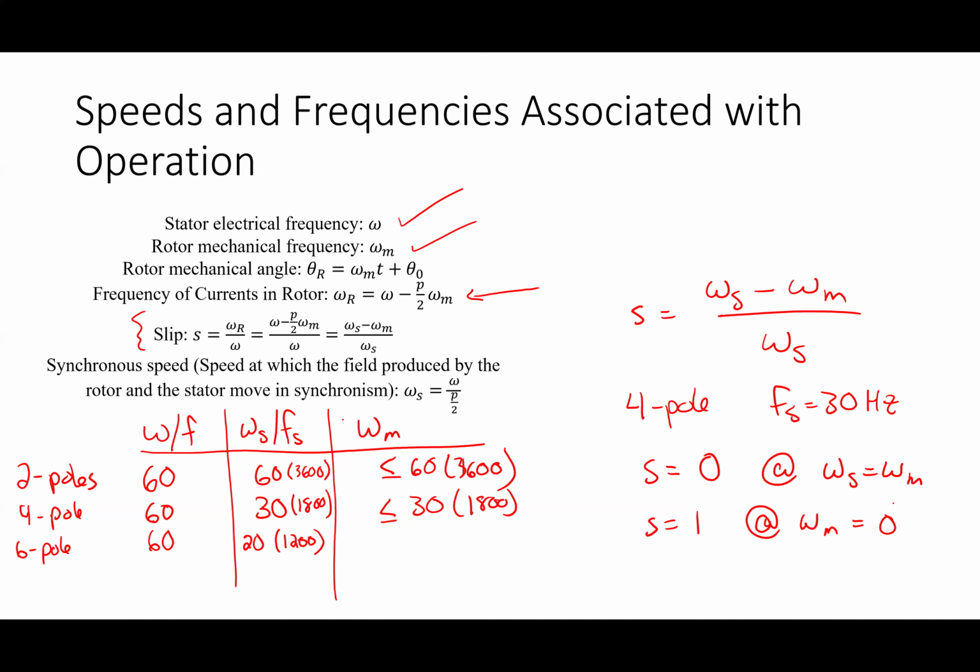So essentially the slip is going to go through that range. In all of these circuit models, look at what you're dealing with in the DC machine. The DC machine has that voltage source, K times omega M. The synchronous machine that you're dealing with now has a voltage source with omega M IF, which is a phasor in that case.